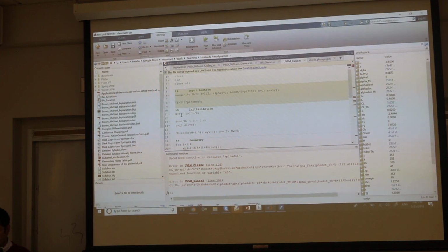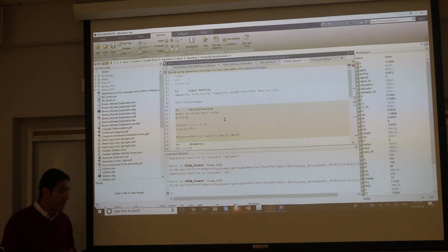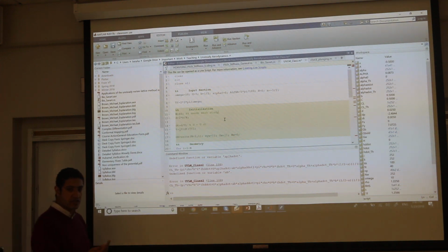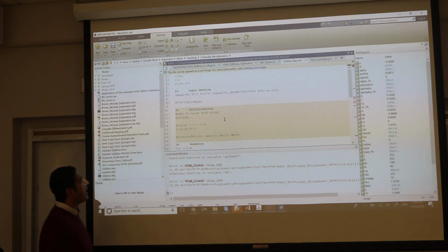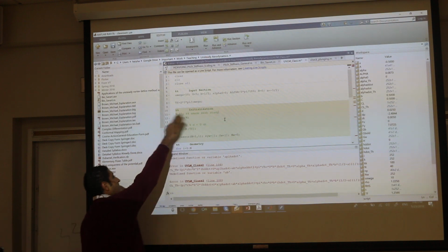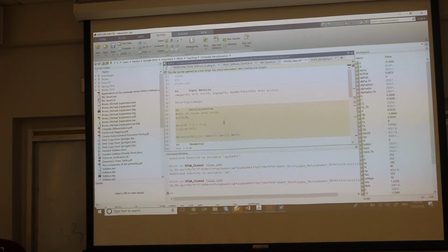Then here is initialization. We need to choose the number of time steps. So actually, this will need some study, right? Need mesh study. So we will do it for maybe 40 or 30 or 20, but formally speaking, you will have to take this code and make a convergence study, to run it for n equal 20, 30, 40, 50, and see when adding more panels does not enhance much your solution, so you stop, okay? We actually did that and we found that 40 is not bad, so you might need to do it again. But anyway, for general code, you have to do mesh study here.